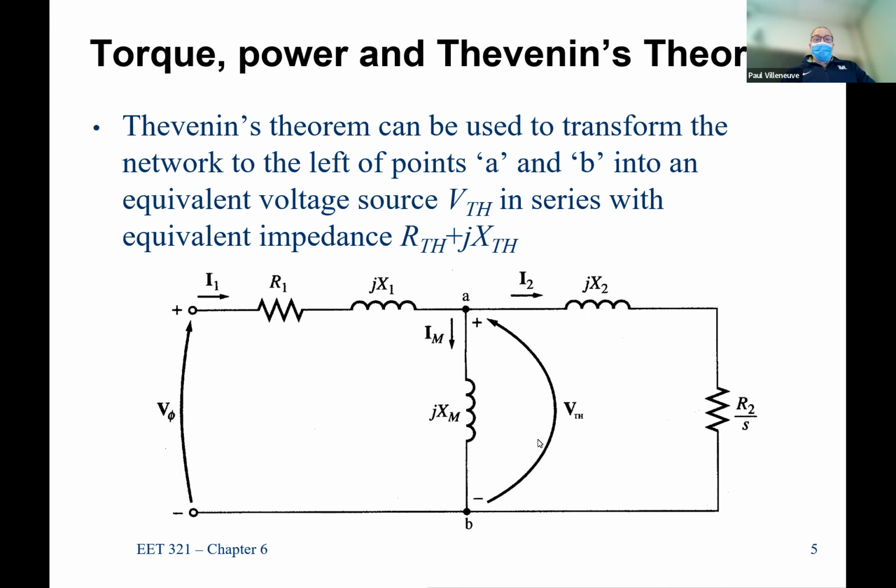All right, so we're going to look at a Thevenin equivalent, which means we want to find the Thevenin equivalent seen across these 2 points. The concept of Thevenin equivalent is that you can replace any set of elements by taking a voltage source, finding the open circuit voltage at that point. That's step 1. That's the Thevenin voltage. And then to find the Thevenin equivalent impedance, you look at the terminals and see the impedance that is reflected or exists there.